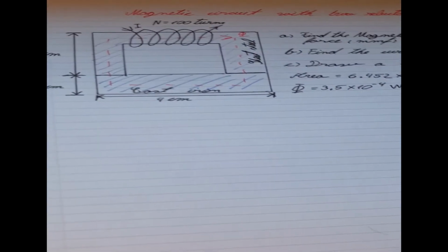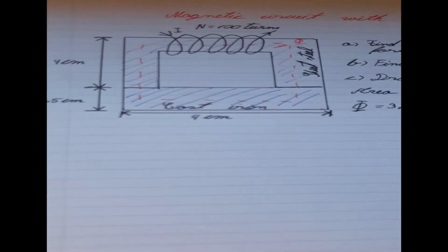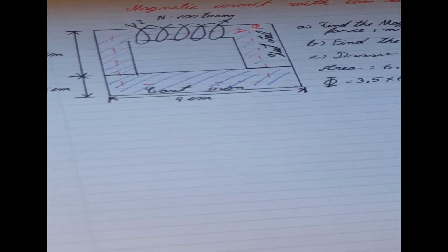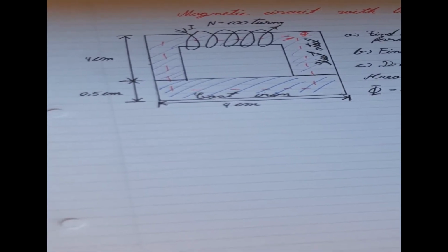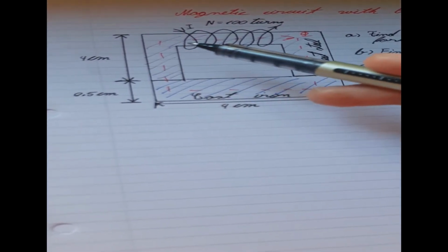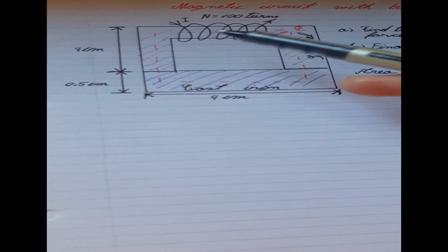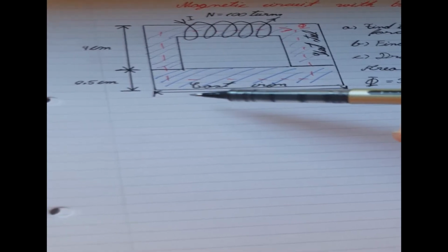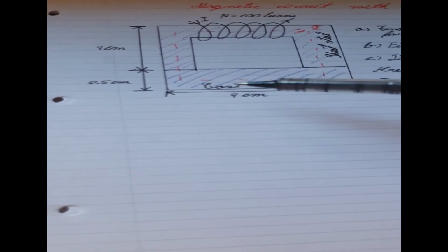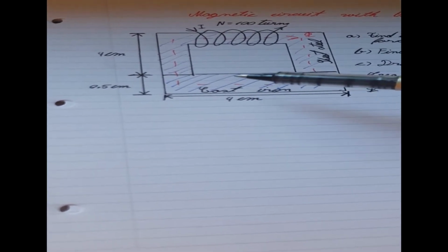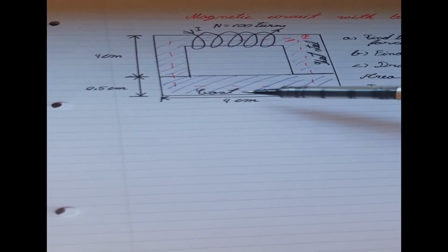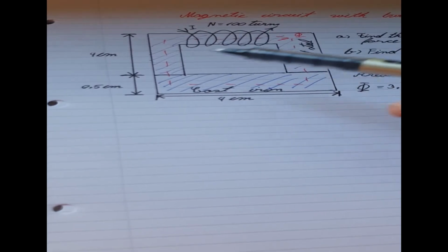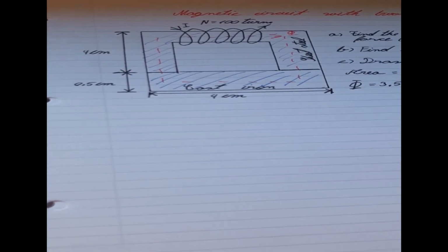And a big part of solving these problems is to know the length. So next step, we'll calculate the length. You may say, well, the length is just this value plus this value plus this value, just the size of the square, and that's it. But no, it's not like that. It's important to know specifically the length for each one of them, the length of the cast iron and the length of these two, which is the steel sheet.